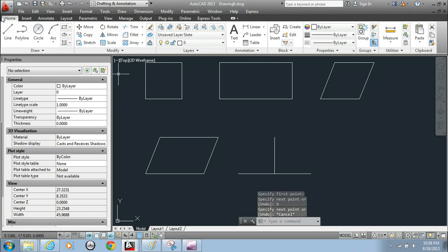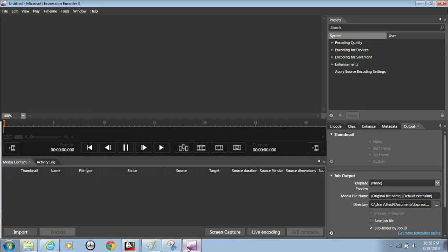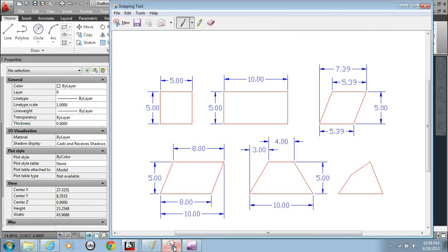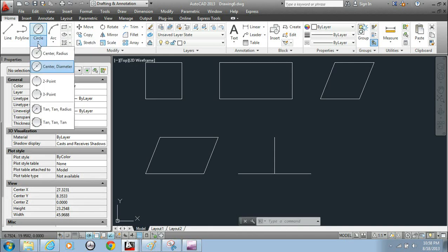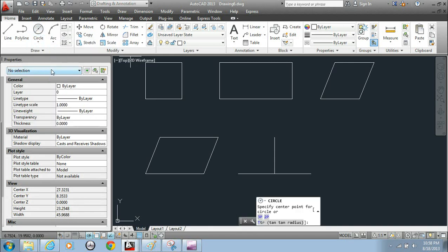And now let me do something a little different. Let me draw a circle. Circle has a diameter we can use. Imagine a circle right here. We just drew a line from this midpoint to where this midpoint is going to be. Let me construct this with a circle. I'll show you how. I'll use the circle command with the diameter option.